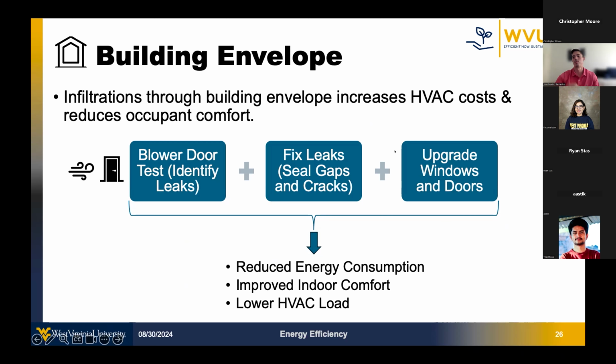First, you can improve insulation by fixing leaks and sealing gaps and cracks. Sealing any gaps and cracks in the building envelope will help prevent air leakage, improving energy efficiency. Adding or upgrading insulation in walls, roofs, and floors can significantly reduce the heat being lost. Also, upgrading windows and doors minimizes drafts and prevents heat from escaping.